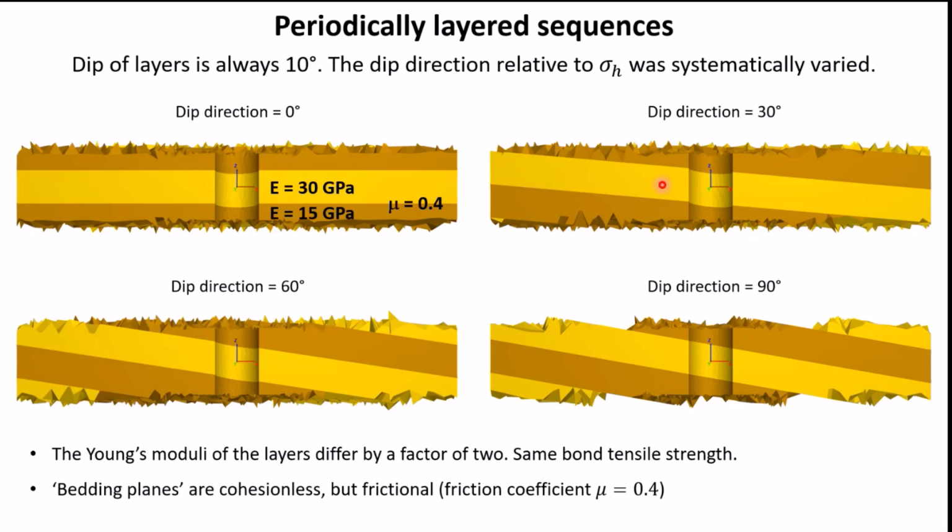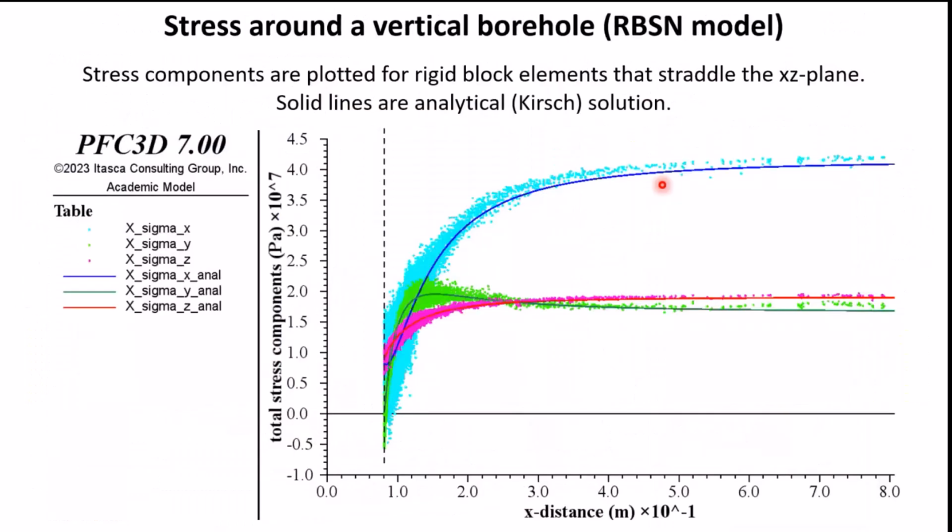You've got fewer contacts per element. Very simple. It's simpler to generate the mesh. And yeah, you have a bit more scatter. When you have a look at the Brazilian test, you get less scatter with Voronoi, but simply because you have more contacts per element. But what matters is the bulk behavior of that material. So I think that's fine.